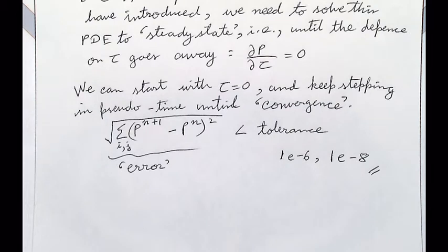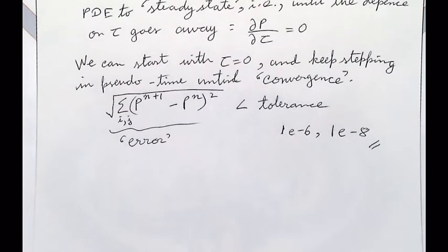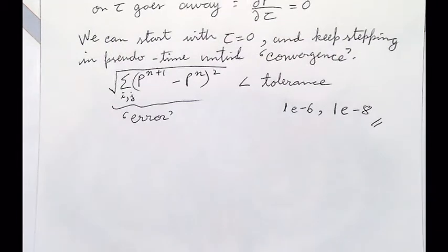Okay, so now you know what pressure projection is, what these intermediate velocities are in the fractional step method, and you know how to solve for the pressure from the Poisson equation. Fine, this gives you the pressure. Remember what the last step was? We were trying to solve the velocity field in the Navier-Stokes equations. So we managed to solve the pressure, but not the velocity. How do we get the final velocity?